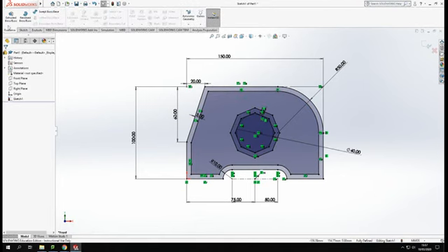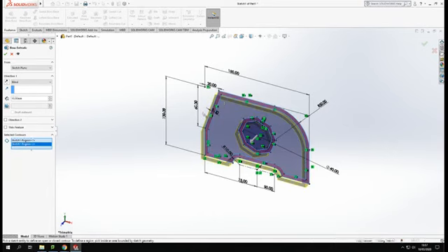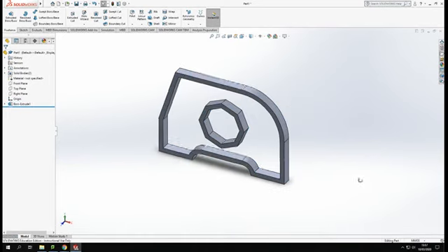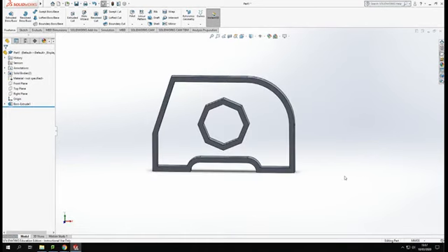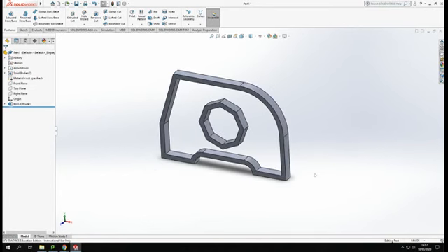Now, to add to that, I'm just going to put an extrude in just to show you the outline of these shapes. Because I've created lots of different shapes here all together, it's giving me the option to pick up multiple contours to extrude. So I can click that one there, and click that one there, and tick, and I've got that shape as a 3D model from that sketch that I've created.